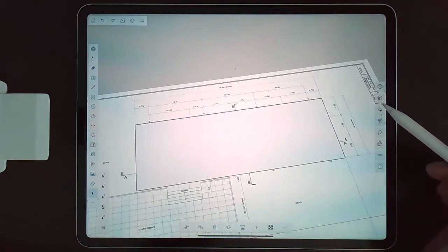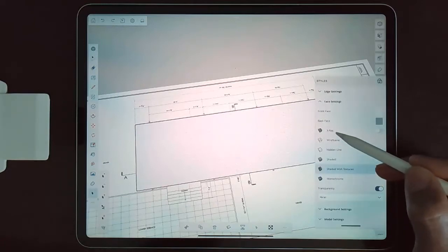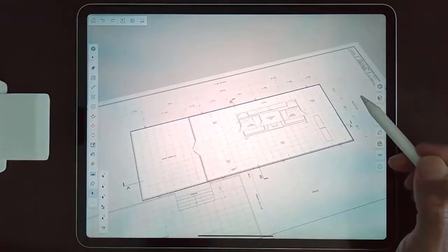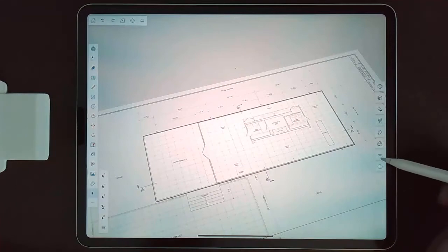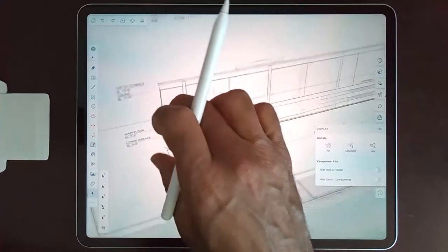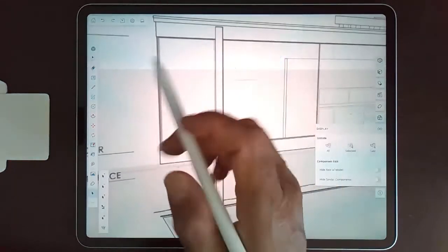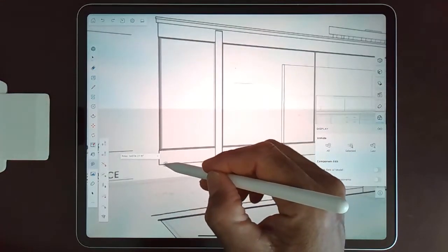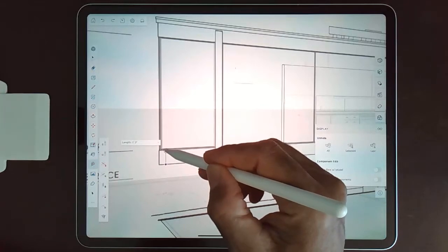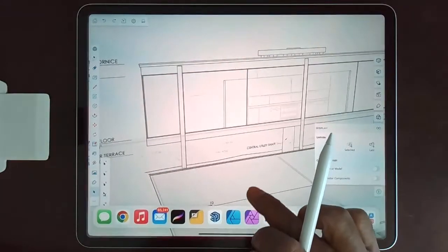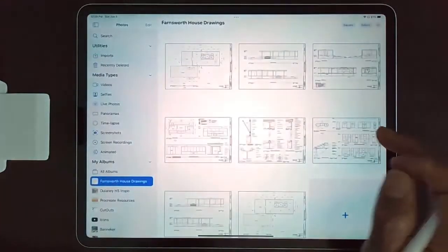The other thing I like to do as I'm drawing this, just as I begin to draw, is change the styles and change the face setting to X-ray mode. What happens is that you're now able to see through your geometry into the drawing, and when you're starting to model, it helps me being able to see the reference drawing behind the modeling. Now, obviously, when your drawing gets very complex, this begins to lose its value because there's just too many lines in the way. But when you're starting out, it just becomes a quick way to be able to see all of your drawings and the modeling at the same time.